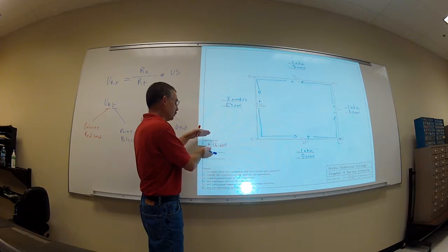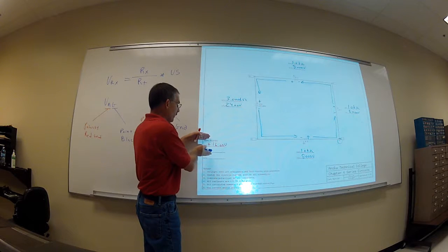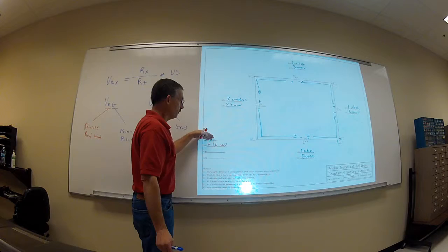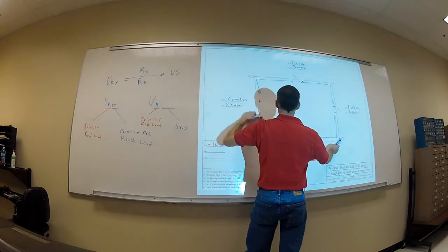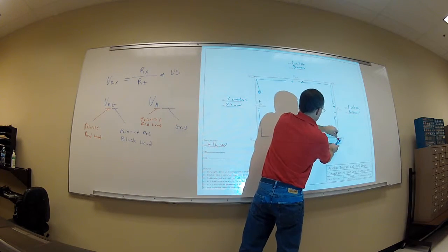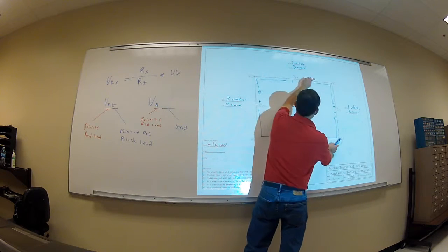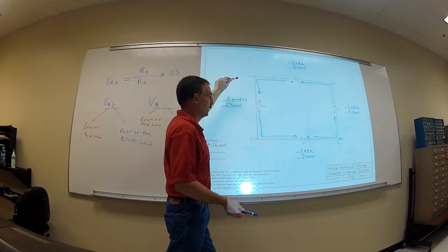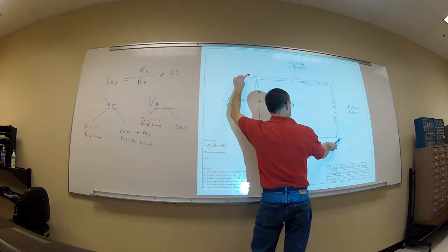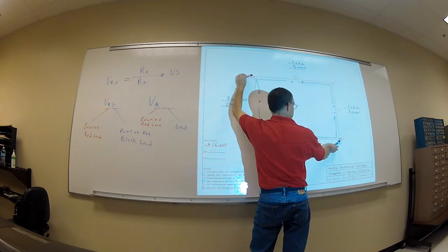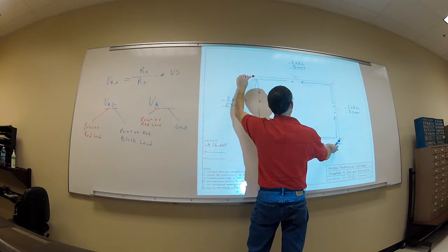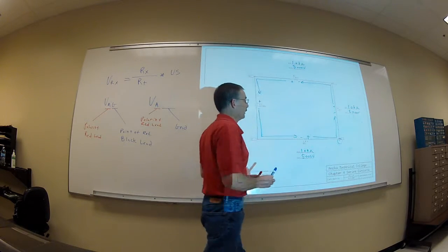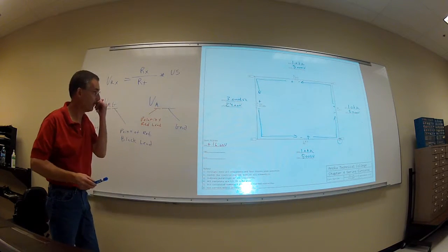Okay? So if we're drawing up schematics, building up a prototype board, and we're giving them some troubleshooting test points on our schematics, that's what I'm going to do when I'm setting up those test point voltages, so I can tell somebody a good test point voltage should be 16 volts. If the next person comes in and they're running into problems, and they identify that I don't have 16 volts at this point, or that I don't have 8 volts at that other point, they're going to know that there's something wrong with that circuit.